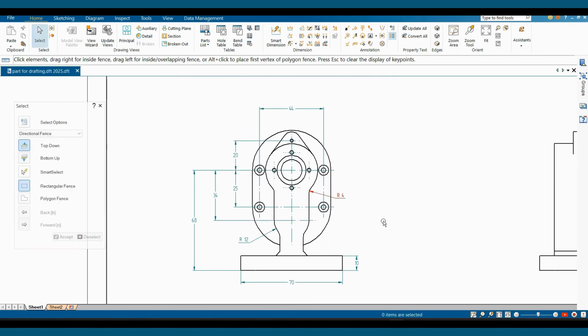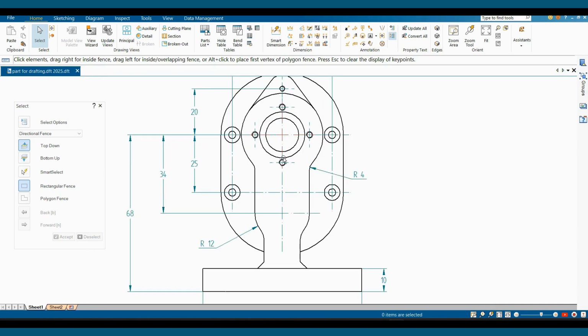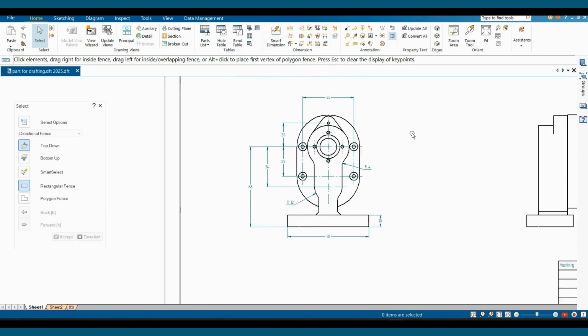After adding some dimensions, we are going to see how to edit the text size, how to flip the arrows, how to add the trailing zeros here, as well as how to change the precisions. We can also add the lines for connection of center point with the radius. We'll see all those modifications now.